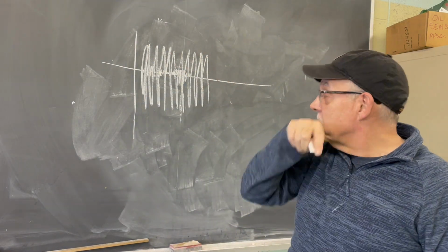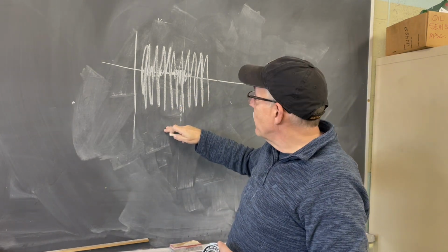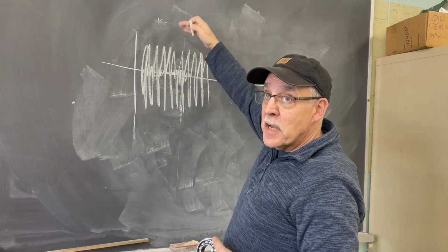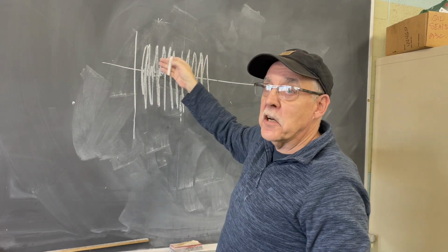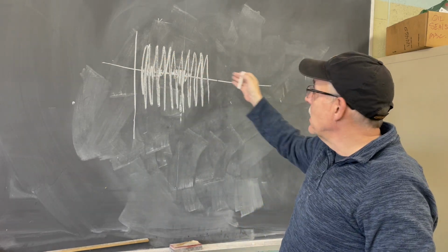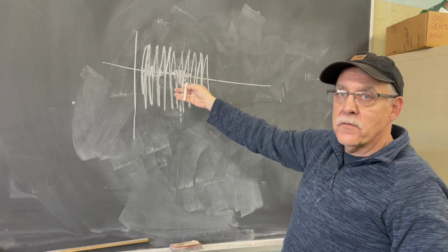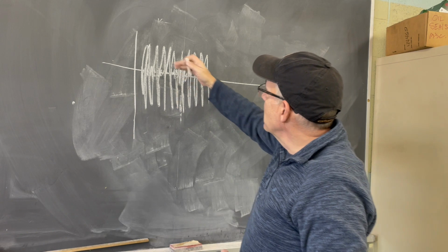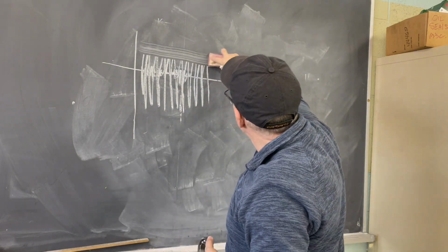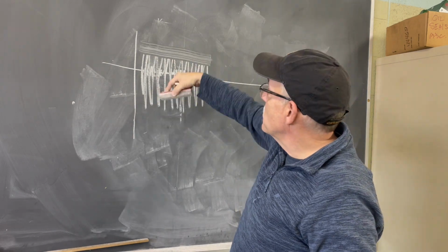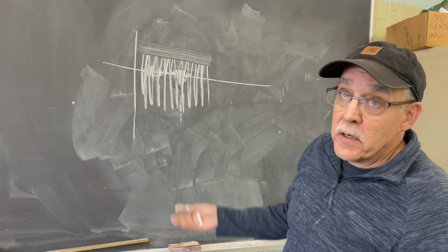That's another thing, how we can tell how severe a bearing is. If you've got way more movement on one side of the waveform than the other, so that they're not the same on either side, that's another example of how severe the bearing is. So that's another indicator that we could just get from the complex waveform. I haven't done any analysis. I don't know what frequency, I know nothing. I'm just looking at the raw waveform from the box, and I see that one side goes way farther than the other side from the neutral position. Once again, that's an indicator of how severe your bearing fault is.